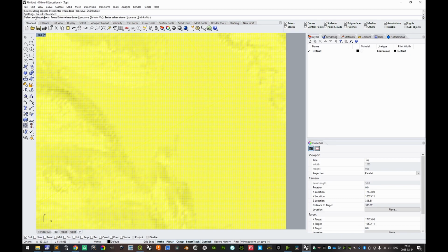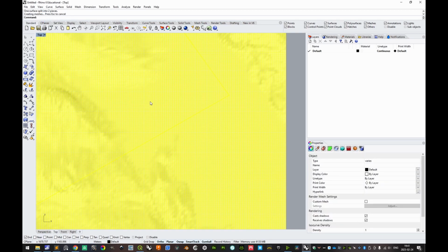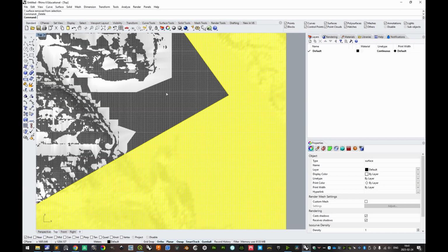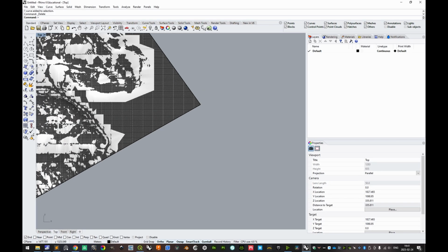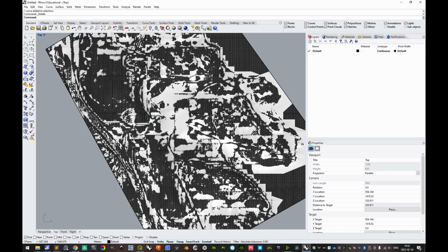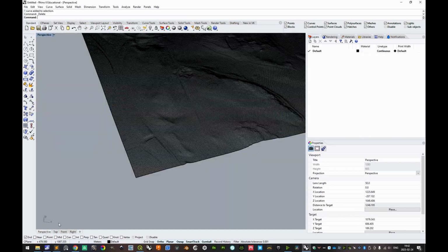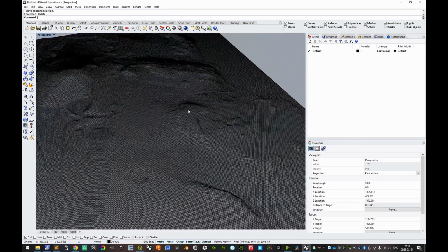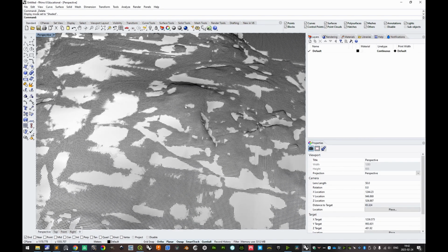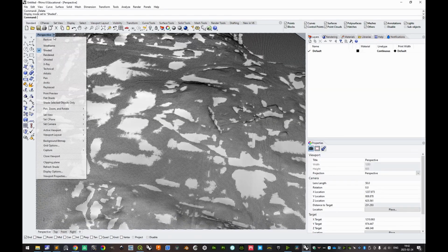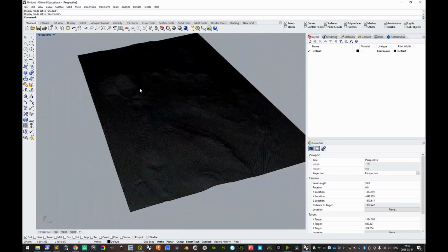And then having split those and waited for the implicit render meshes to be generated as well, we can control click the interior and delete the exterior. Very good. We can delete that curve as well. All right, and this has serious mesh generation errors. When looking in shaded view mode or in wireframe view mode, we see the control curves and they look very good, but the mesh generated implicitly is not very good.